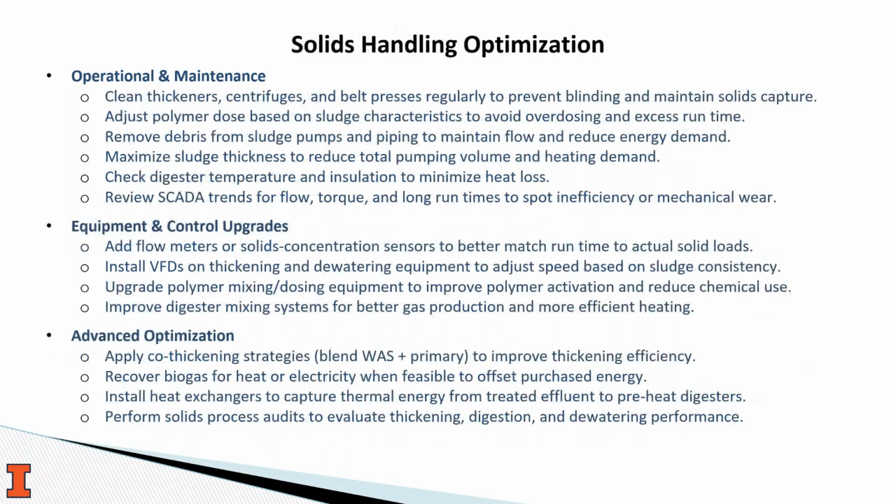Solid processing is another significant energy user. How can you improve those? Well, for the low cost, no cost strategies, keeping thickeners and presses clean prevents blinding, while optimizing polymer dose can prevent unnecessary runtime. So definitely make sure your solid processing equipment is being cleaned routinely.